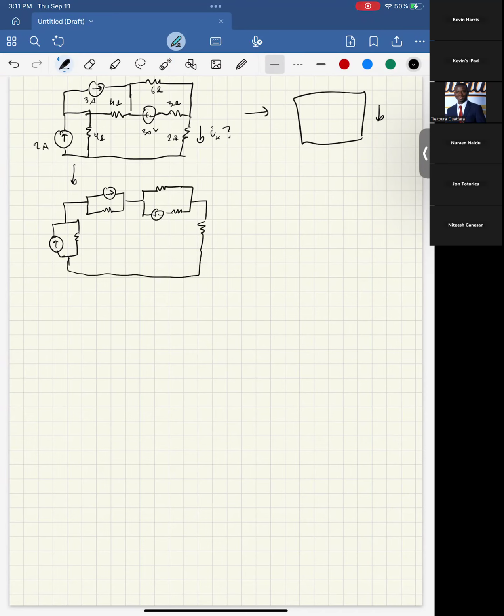So if you look here, all of the points on this circuit have all the same connections. I've just changed what the wires look like. All of the connections here, like this connection here is the same as this here, and likewise, this here is the same as this here. All of the same points on the circuit are connected. It's just the wires look different now. And hopefully now it's pretty clear to see, okay, I can do a source transformation here, here, and here.